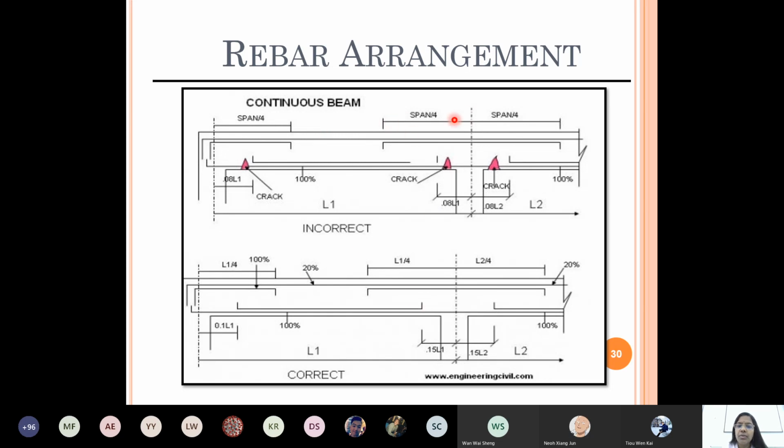Okay. This one, when you check, these are the reinforcement details. This is the thickness of the beam, right? Thickness of the beam, this is the column, right? You will do this part later and don't have to worry, but have an idea about how the drawing will look like. This is called reinforcement detailing, okay? It will have the size of the beam, the reinforcement, whether top and bottom or only at the bottom, and this is called crack inducer. They provide purposely a groove-like structure. Later you will know what it is.